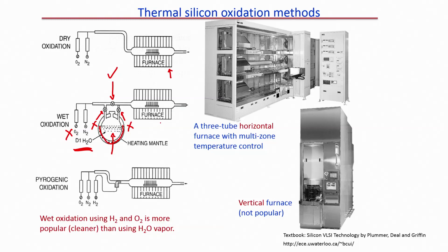And once we reach the appropriate temperature, say 1100 degrees centigrade, then what do we do? We keep this open, we stop nitrogen, we start oxygen, we close this valve, and open this valve and open this valve.